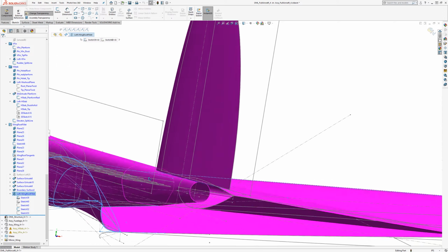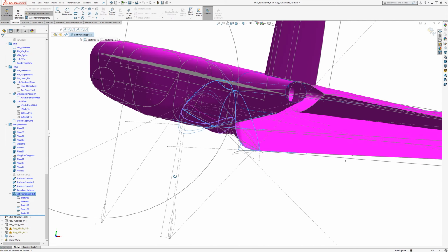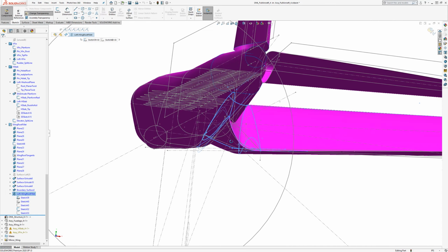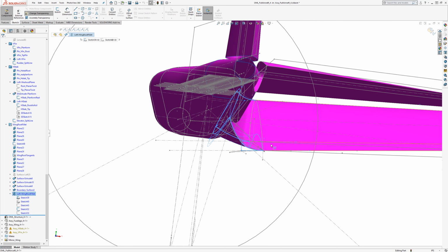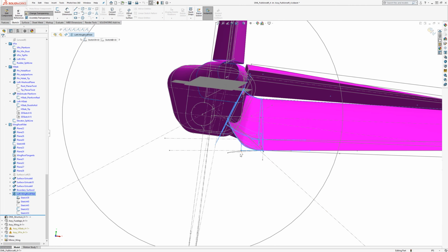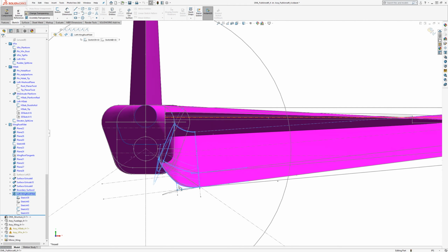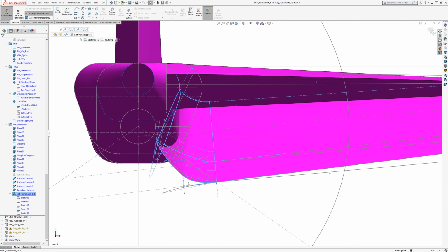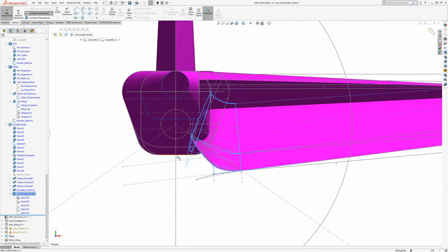And in the end, what that does is, for a low wing, there really is quite a drop in where your trailing edge is compared to where your fuselage is often, especially for a big chord. That's why I'm actually going to change this design probably to a mid-wing.